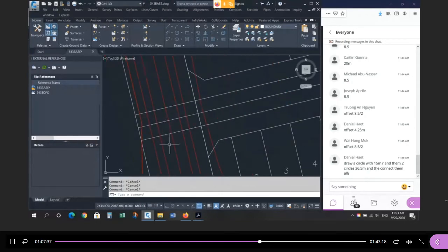Okay, so let me turn off a couple more things. I'm going to turn off the embankment layer. I'm going to turn off the shoulder. And this is the boundary, I think. Yeah. So now I have center line of the existing road. I have edge of pavement on the existing road, edge of pavement on the existing road. And then for the proposed road, I have center line, edge of pavement, and edge of pavement.